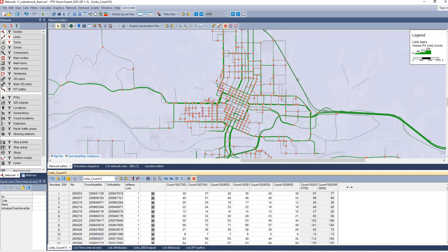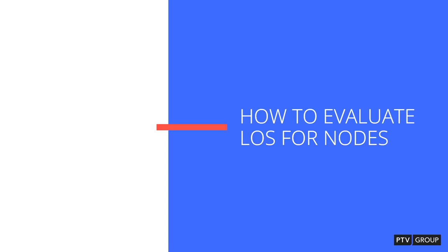So I can also list the attribute in different time definitions in listings. That makes it easy to compare those data to results of the assignment, for example. So that is a way how you can make use of time intervals in Visum, in particular to compare results.